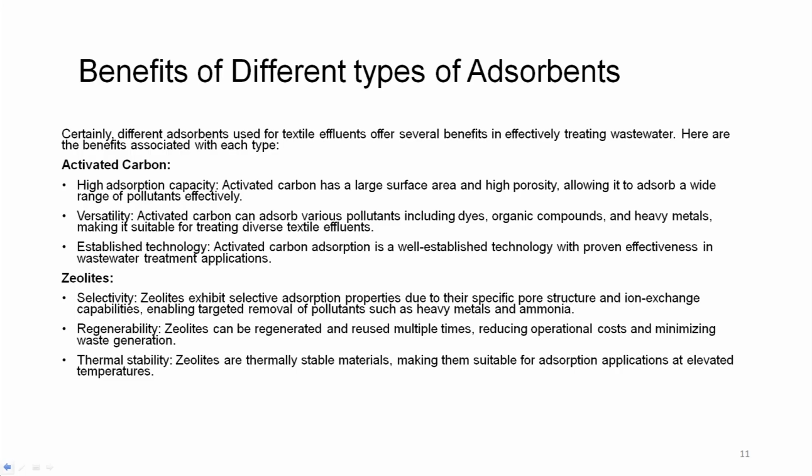Zeolites can be regenerated and reused multiple times, reducing operational cost and minimizing waste generation. And we ourselves have used different types of zeolites for the removal of color from the textile effluent, and it works very well and can be regenerated very effectively. Thermal stability. Zeolites are thermally stable materials, making them suitable for adsorption applications at elevated temperatures.